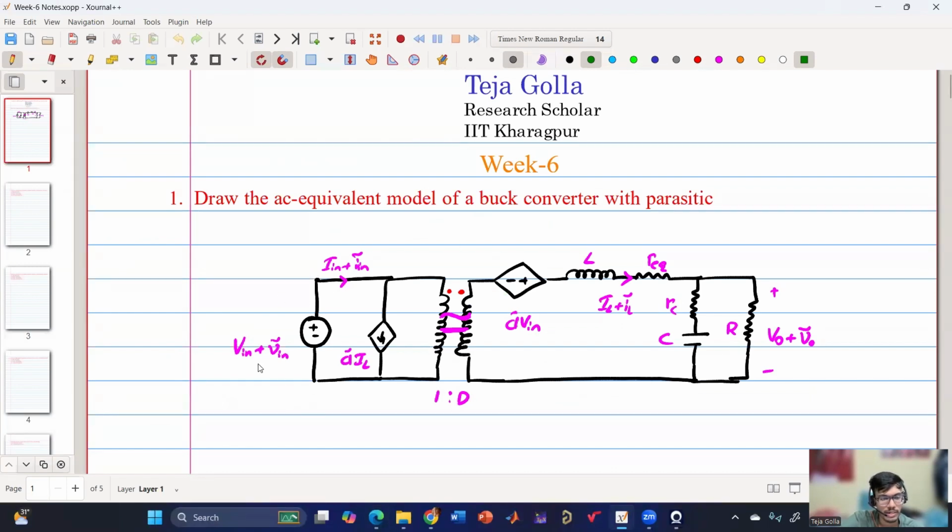So we have the input perturbed around the operating point V, and the other terms are what we have obtained in the process of averaging and perturbing the dynamics. And these are the inductance, capacitance, as well as load R. And if there is a current source, then I can also add something like this here. So there is a constant current source. So load can be anything: constant resistive, constant voltage, or constant current. So here I'm considering a constant current I naught plus I naught tilde.